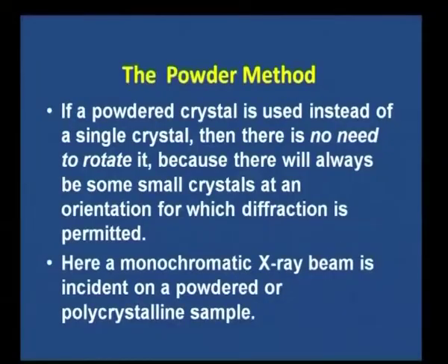So, now let us move on to the powder method. What is powder diffraction? Powder diffraction means that instead of a single crystal you will be using powder. Powder is not a single crystal; it is an agglomeration, a collection of different tiny crystals. Here you can use a single wavelength.